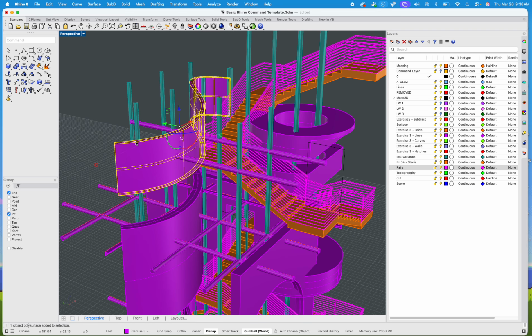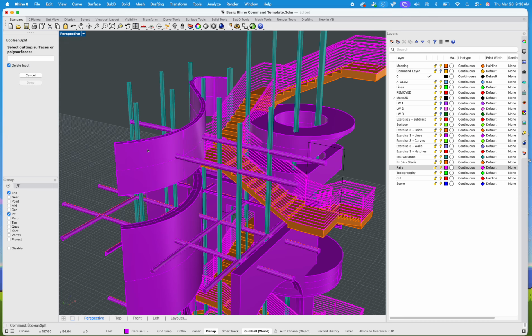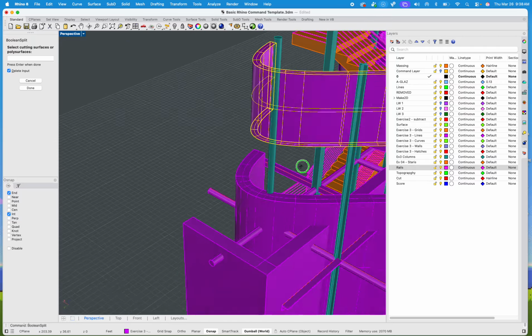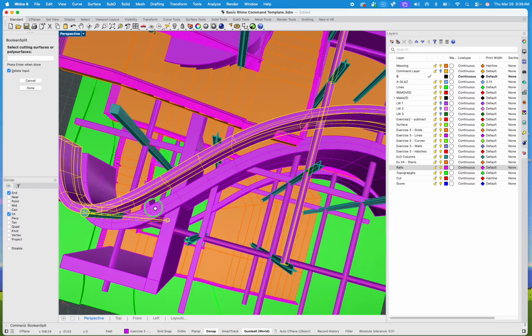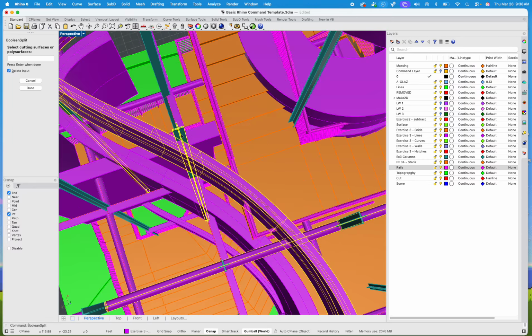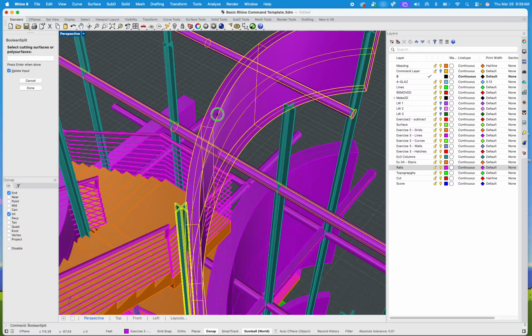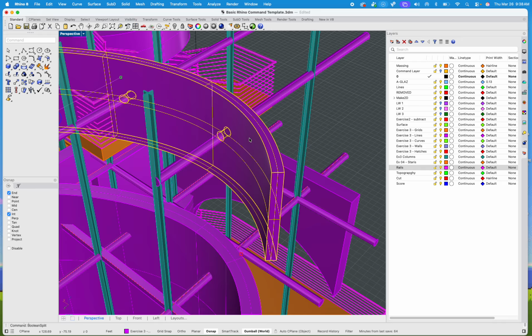So the way that I want to do that, you guys already know it, Boolean difference or Boolean split. In my case, the wall and these columns. So I'd probably get every single thing that's locking into this. So I'd probably want to remove that one. My shapes are going to get real funky, so I do apologize for the sake of tutorial. But yeah, that's looking good. All the parts that basically touch that wall. And press enter, and voila.